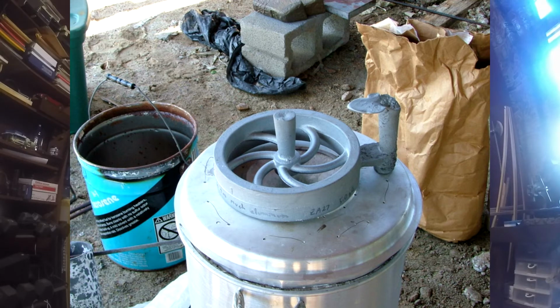You're going to get at least a little bit of turbulence, and you're going to be manufacturing some dross. Dross is a combination of the metal that you're pouring and oxygen. When you splash it around like that, the oxygen attaches itself to that metal, combines with it, and you wind up having something that looks like a metallic oatmeal or a metallic mess of fiberglass. It doesn't look great.